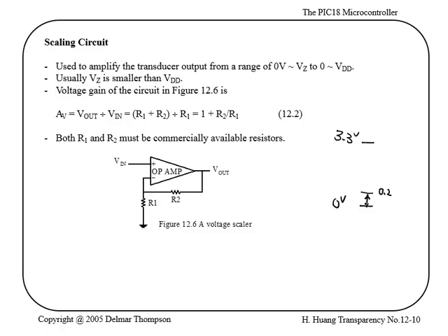If your sensor only gives you up to 200 millivolts, and if you ask your PIC to divide this 3.3 to 0 into 1023 segments, then you're basically wasting the capabilities of your A to D conversion, right? You're not going to get a 10-bit resolution here. You're going to get only 0.2 divided by 3.3 of the range.